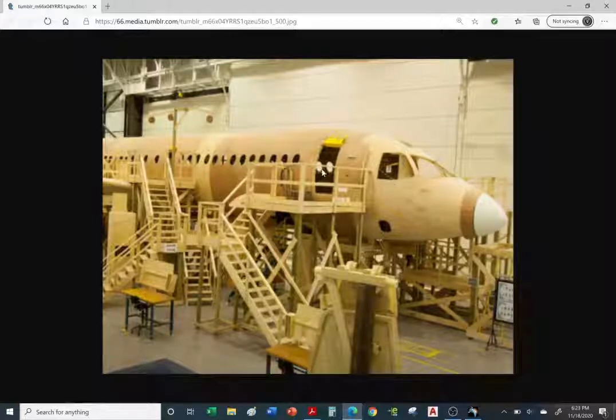When there's installation going on, sometimes you need room to install rivets or bolts and nuts, and you're going to need wrenches. And then sometimes there'll be tight spaces where you try to get a wrench in to tighten a bolt or a nut, for example. Okay, so it's always a good idea to come up with a mock-up and not find issues later on when you're doing the actual assembly at the assembly plant.